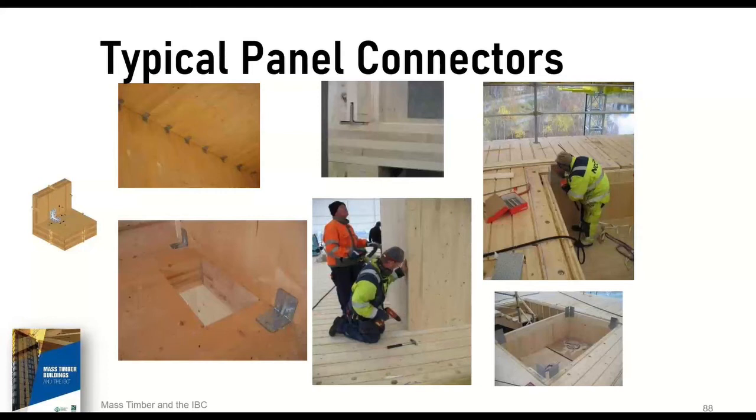You'll notice in the one case the electric screwdriver used in the center picture there, and also when you start thinking about installing the connections at the laps, the screwdrivers that you'll get are bigger and longer and designed so that the carpenter doesn't have to bend over. So he's able to install the screws while standing up, helping save on wear and tear on the body.